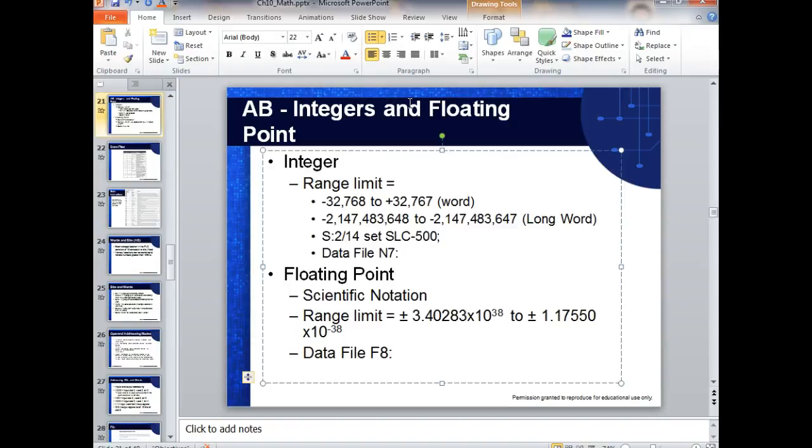If the most significant bit is a 1, and we're using signed math, it's assumed to be a negative number. Right? You understand that? If the most significant bit is a 0, it's assumed to be a positive number. Well, the problem is, if you got 0, the most significant bit is going to be a 0, but 0 has no sign. 0 has no weight, so it's considered not to be either a negative or positive number. So this is why we have one more negative combination than we have positive combination, because 0 eats up one of your positive combinations.